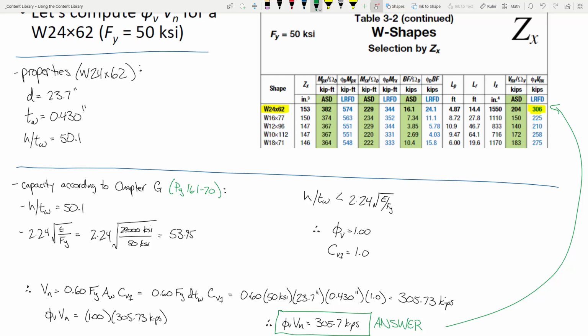The thing that's kind of crazy is that normally when we think of buckling, that's it. You load it, it buckles, it's done. That's not the case with shear. The reason is that in shear, the entire component that is undergoing buckling is fully restrained on all 4 sides. So the crazy thing about shear buckling is that you can keep loading it. You can actually keep loading it after it buckles.